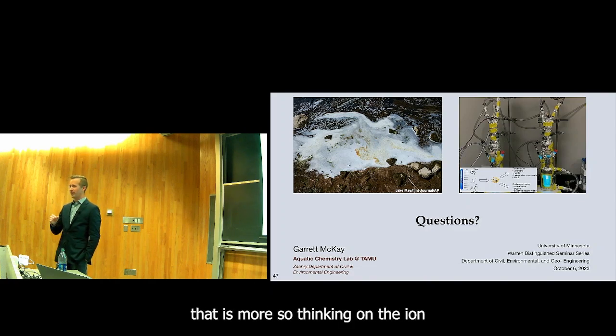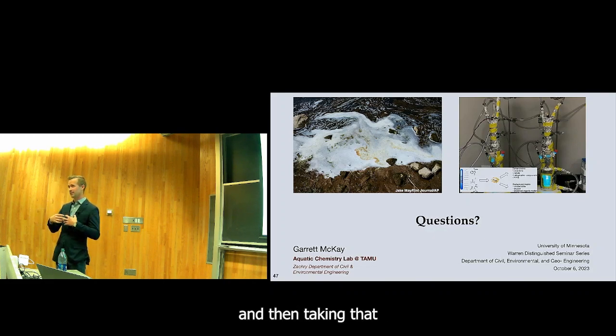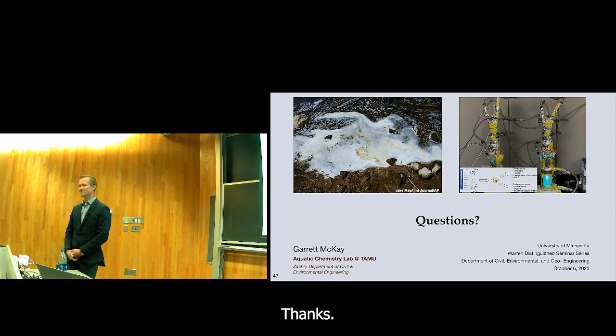Where we're going with that is more so thinking on the ion exchange system. So right now we're working on taking PFAS-laden ion exchange resin and desorbing with alcohol, base, and water, and then taking that really concentrated mixture and trying to apply the UV sulfite system to that. Thanks. Thank you.